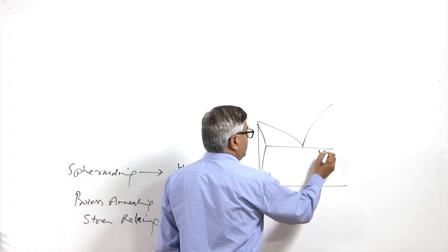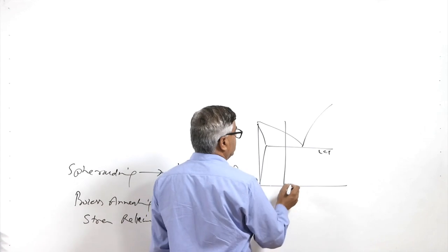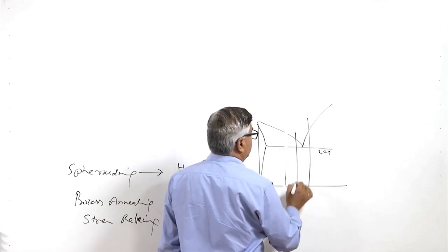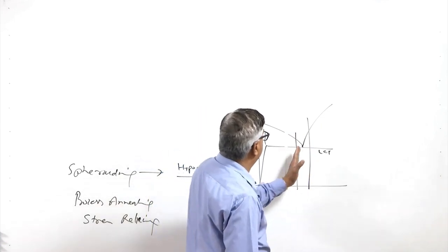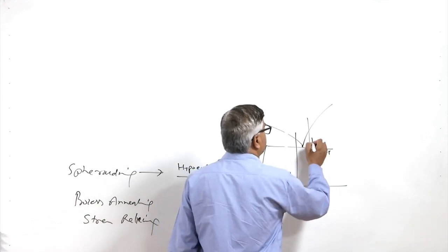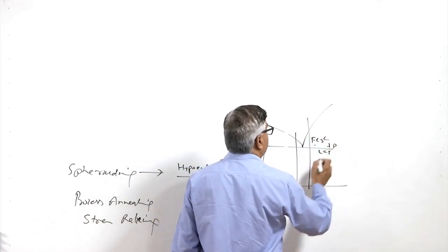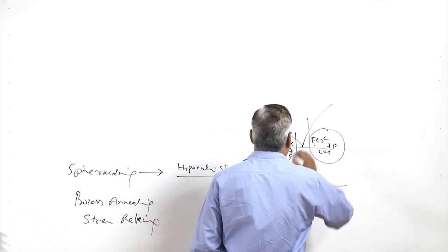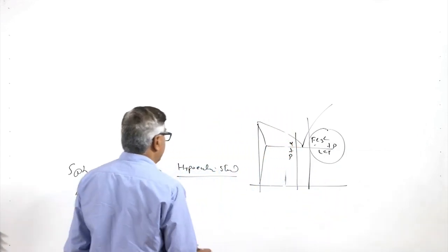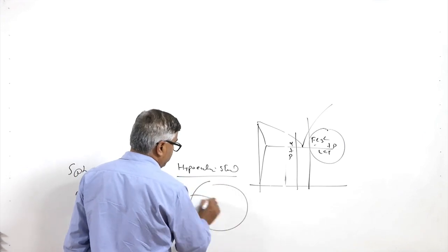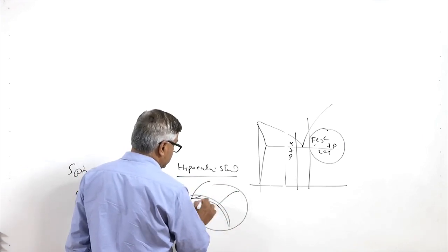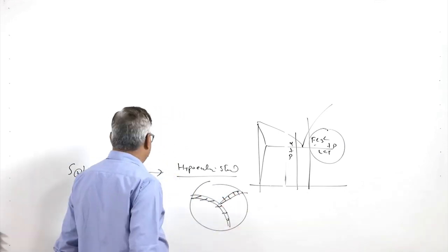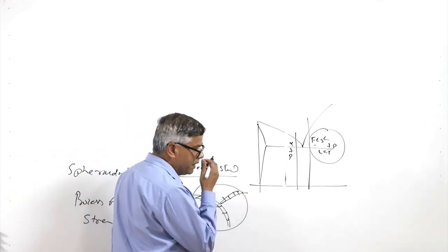this is the lower critical temperature. So, steel of a given composition, like this for high carbon steels or for hypereutectoid steel. In both cases, here Fe3C will be there with the pearlite, and here alpha plus pearlite. So, when it is applied for hypereutectoid steels, we have a thick layer of cementite present at the boundary, which will adversely affect the machinability. So, efforts are made to break this thick layer of iron carbide,